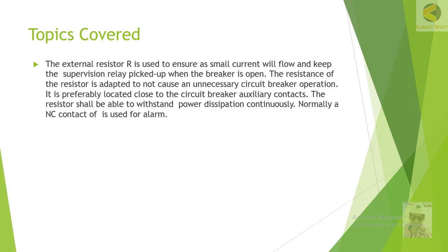The resistance of the resistor is adapted to not cause an unnecessary circuit breaker operation. It is preferably located close to the circuit breaker auxiliary contacts.